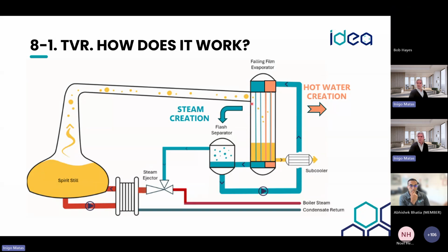What we're doing in this case, this is a falling film evaporator. We supply condensate, which when going down is going to produce vapors, because we are slightly in vacuum. The temperature of these vapors is below the temperature we need. This is boiling at 100, let's say this is like 106 degrees.